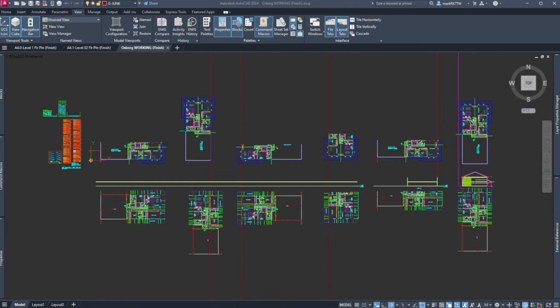And then the width can't be less than 36 inches. Now the handrails can invade on that width. So clear width of the stairways at and below handrail height, including treads and landings, shall not be less than 31 1/2 inches where a handrail is installed on one side and 27 inches where handrails are installed on both sides. So you can see it can invade that space quite a bit.